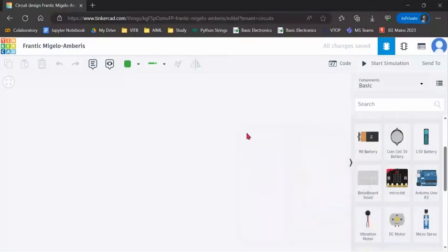Okay. So this is the basic window that will be created once we log in and go to create a circuit. On that, this is the file name that will be created. You can change the name by double clicking. You can have any name. Suppose we have changed it to demo, so it will be changed to demo now.